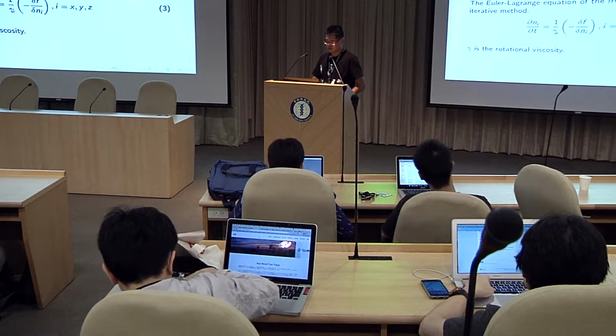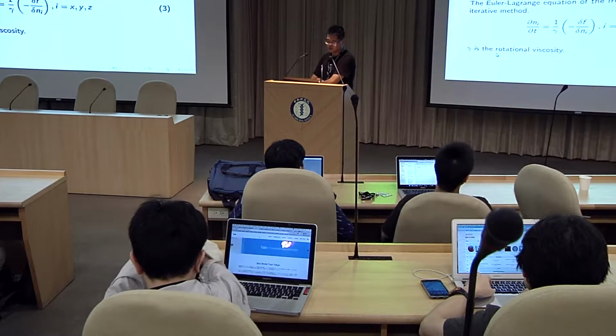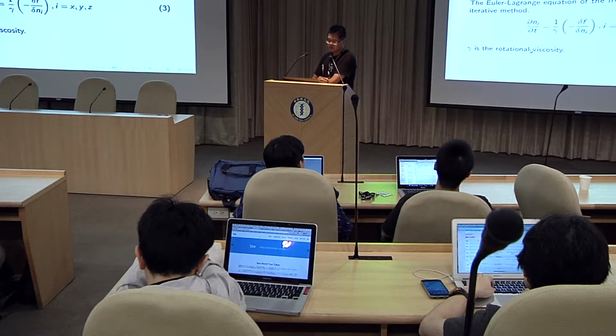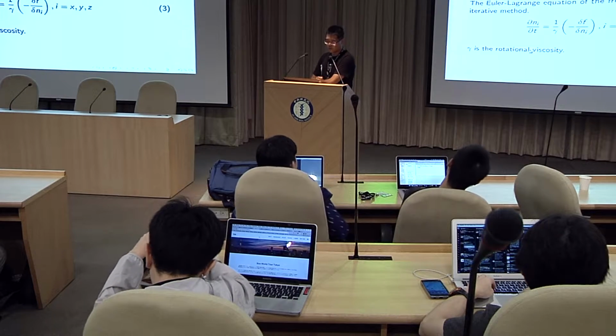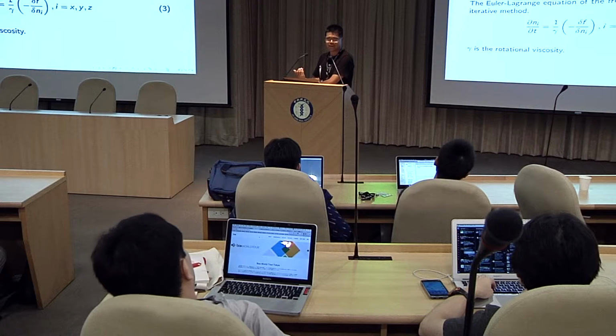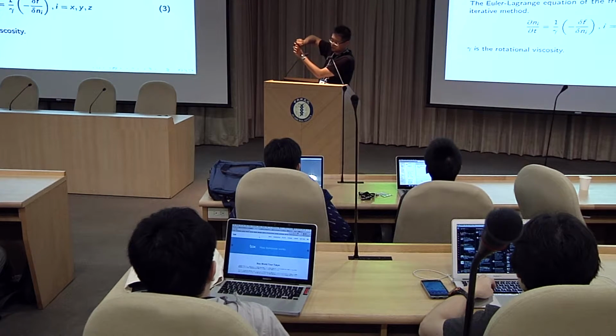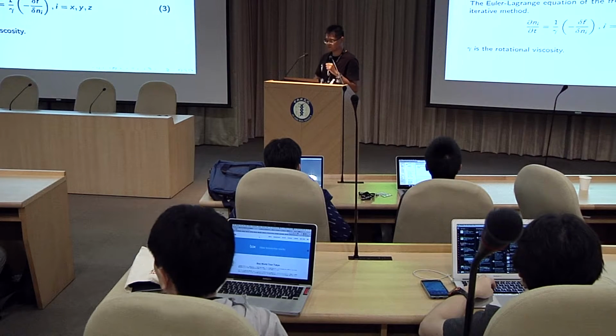Its change is governed by a viscosity, called the rotational viscosity. This is the only viscosity that the supplier can give us. It describes the viscosity when the liquid crystal molecules start to rotate.